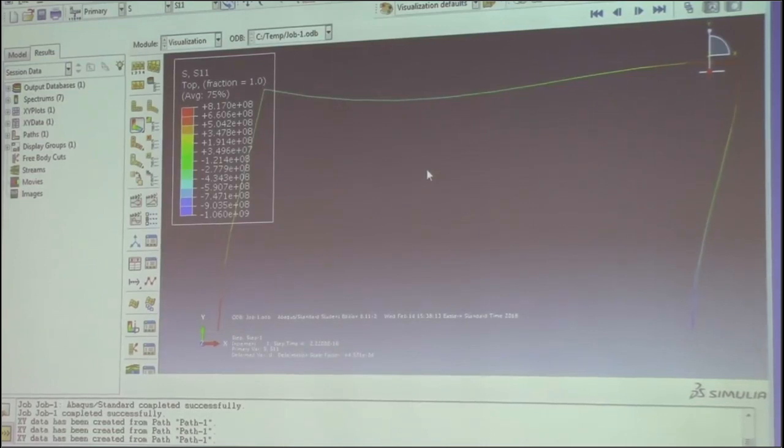So for this 3-beam problem, what is the best way to do the seeding? Is it always that more elements is better, or for some beams, you can just use one element? For some beams, we need to use more elements to do the approximation.